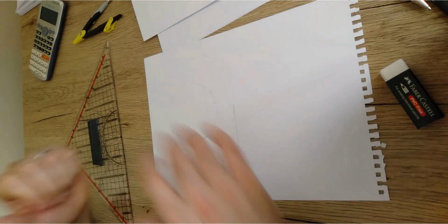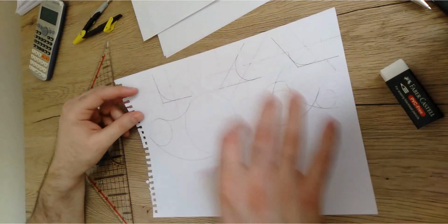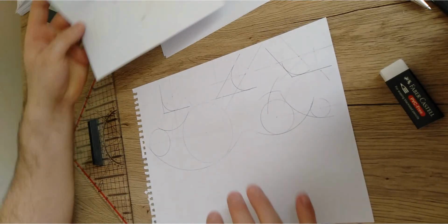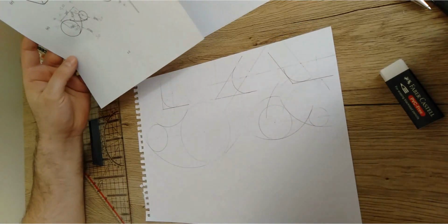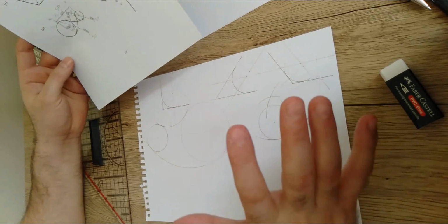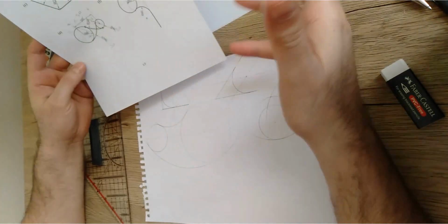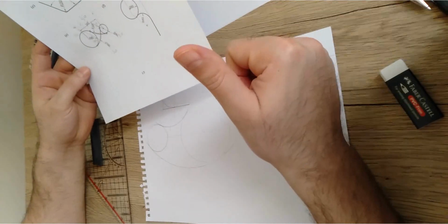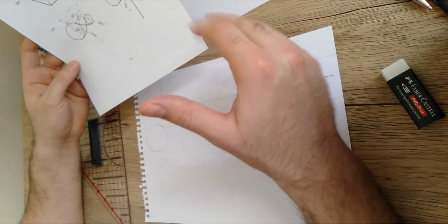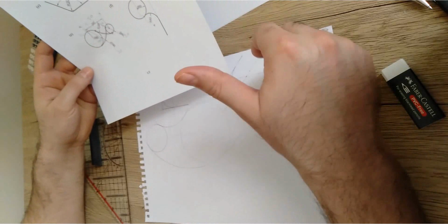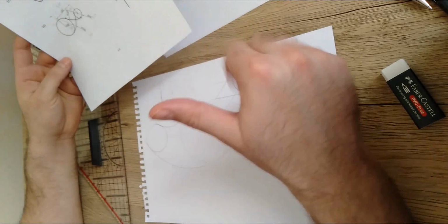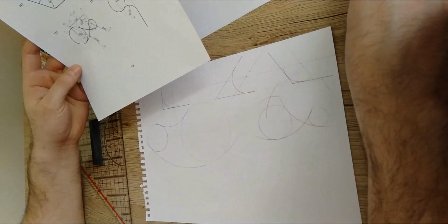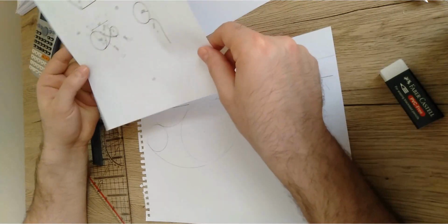All right. So I've created and generated all of these tangencies here, and as you can see, there are lots of lines, and even if you look at it, you aren't gonna be able to distinguish between the baseline or the other lines and curves that are used to assist me to locate the center points of these curves. So it means that we have to do finishing over this drawing, going over these circles and these lines again to make them clear using the 1 millimeter pencil, and this is what I'm gonna do. All right.